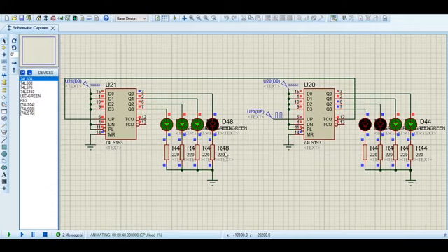Their clocks are connected in such manner with respect to the clock generator because we want to trigger this chip first since it holds the 4 least significant bits, and only trigger this other chip when one full counting cycle of the first chip on the right occurs. With that, the counting will go from binary 0 to 255 continuously, as you can see on the outputs here.